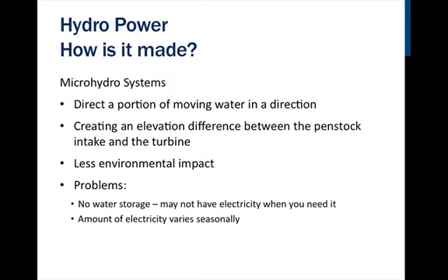In contrast, with microhydro systems, you direct only a portion of moving water in a separate direction. You may have to manufacture elevation difference to create head, which is the difference between the level of the penstock intake and the turbine. There is significantly less of an environmental impact from microhydro systems than a large dam and hydroelectric plant.